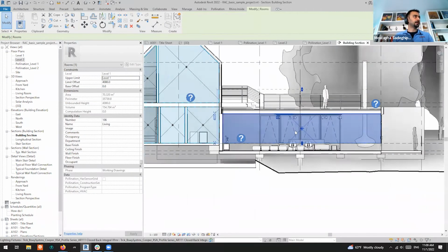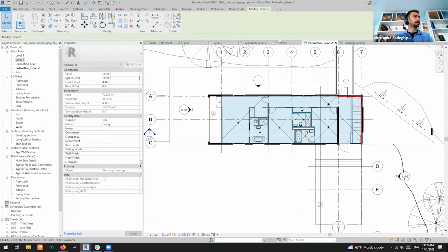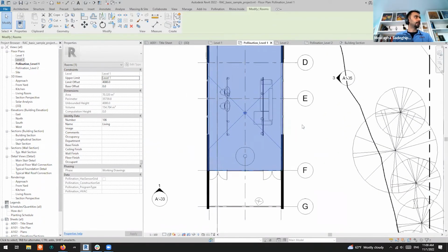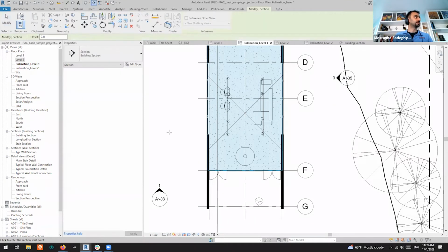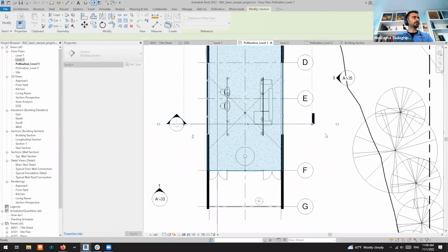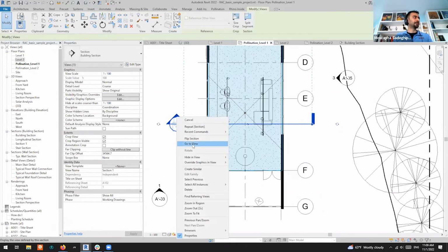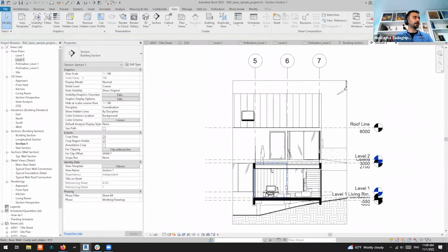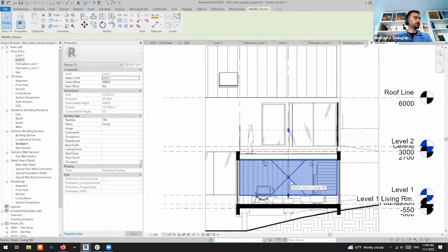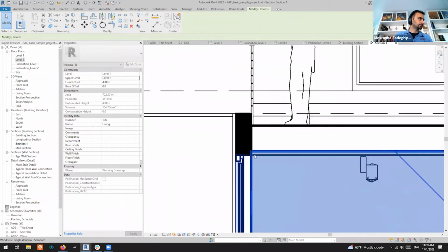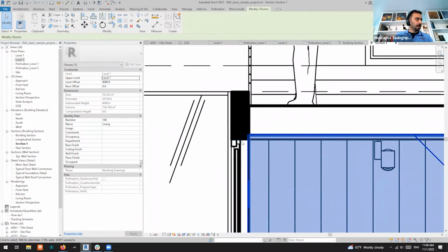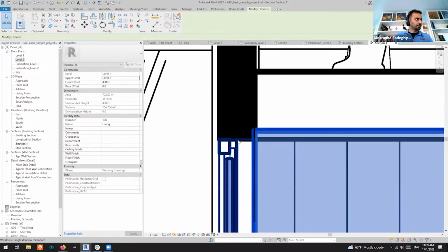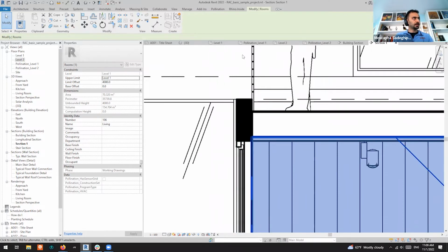And the reason that's happening is, again, if I go to the plan here and draw a section, so I go under view and bring the section and draw it. After you fix a few models, this becomes like, oh, I know this. Every time you have to go do this. Actually, this doesn't show up well here, but the reason this is happening is because of the room and the aperture. You see there is a gap here. This is the place where it's leaking.